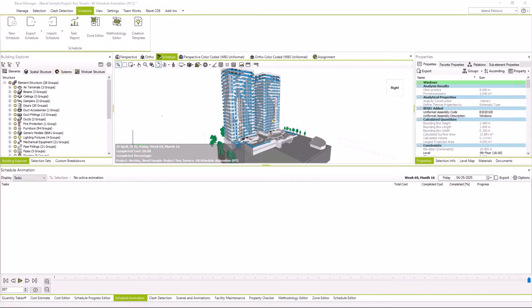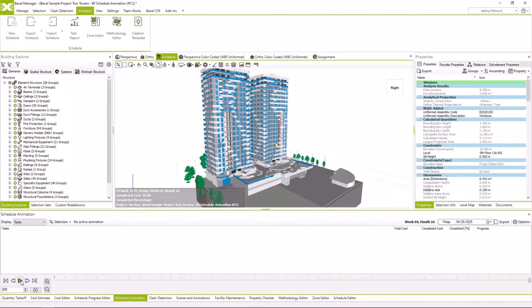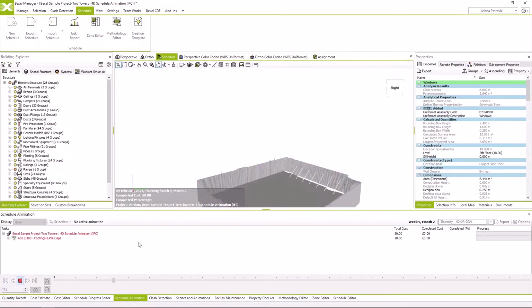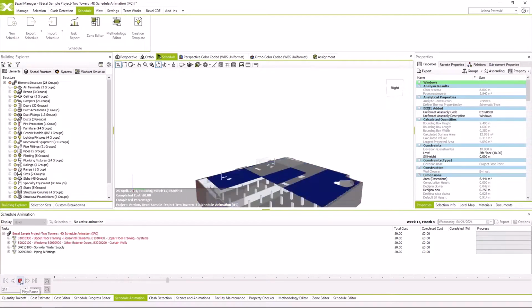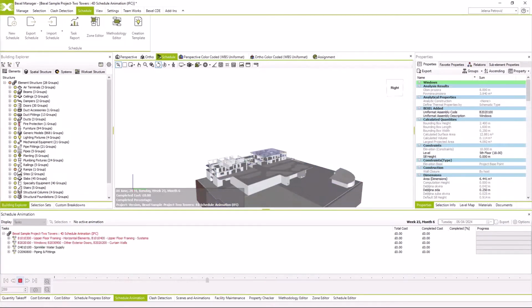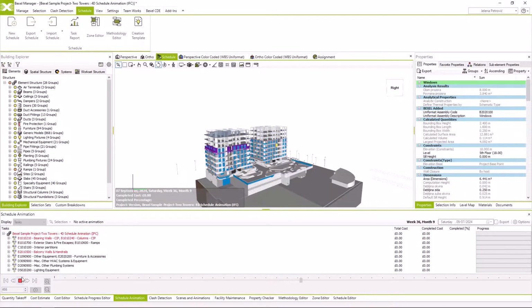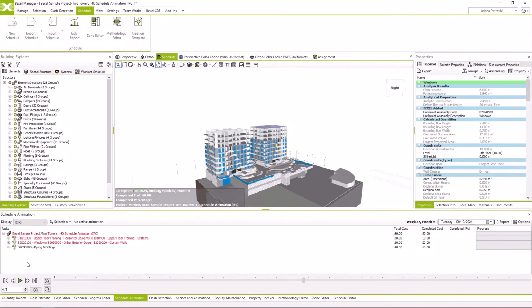I would like to share with you some information. We should pay attention here. What can be the problem? Sometimes the BIM model doesn't have elements distributed in the right levels, or there are no defined construction phases or buildings if the model includes several buildings. Some task durations should be longer than defined here. Maybe the activities are related to prefabricated elements, but the duration is defined for cast-in-place activity.